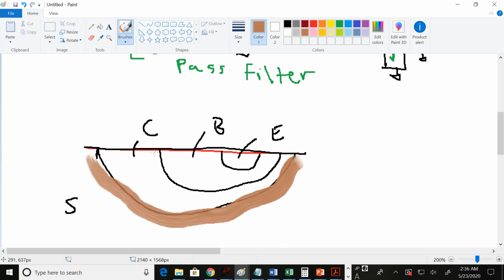So in the forward active region, the only junction that's forward biased and conducting is the BE junction, and the BC junction is off. So you have a depletion region here, and this junction right here is on, so there's no depletion region between B and E. The doped silicon behaves like a conductor. The depletion region behaves like an insulator. And so your collector right here: conductor, insulator, conductor. This actually acts like a parallel plate capacitance.